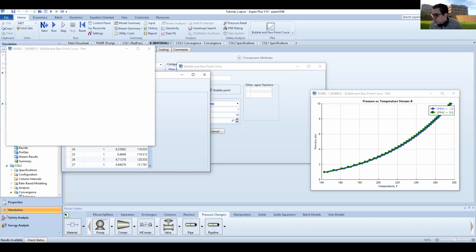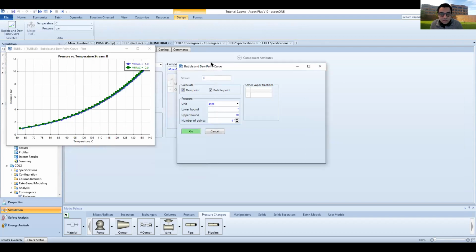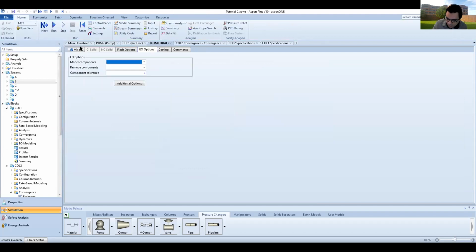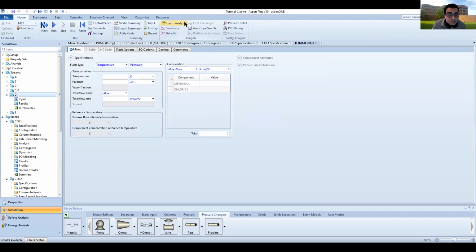Okay, sounds good. And then what's the thermal conductivity of the chloroform product stream? Okay, so let's navigate to the chloroform product stream. Close out all of this. Our chloroform product stream, I think it was, let me just remember, so it's D. Let's go to D. Stream analysis. So we can do the bubble and dew point, get the first thing, and to get the bubble point, you just do this, and then you go to 5.5 bar. You're going to get it.